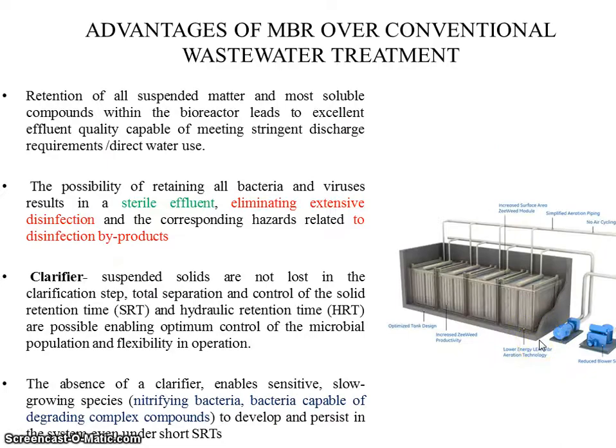Let me go through a few advantages of using MBR over the conventional treatment system. You can retain a large amount of suspended matter and most soluble compounds within a bioreactor, which leads to excellent effluent quality capable of meeting stringent discharge requirements. There is the possibility of retaining all the bacteria and viruses, resulting in a sterile effluent, eliminating extensive disinfection and the corresponding hazards related to disinfection byproducts. All these will be avoided by using MBR.